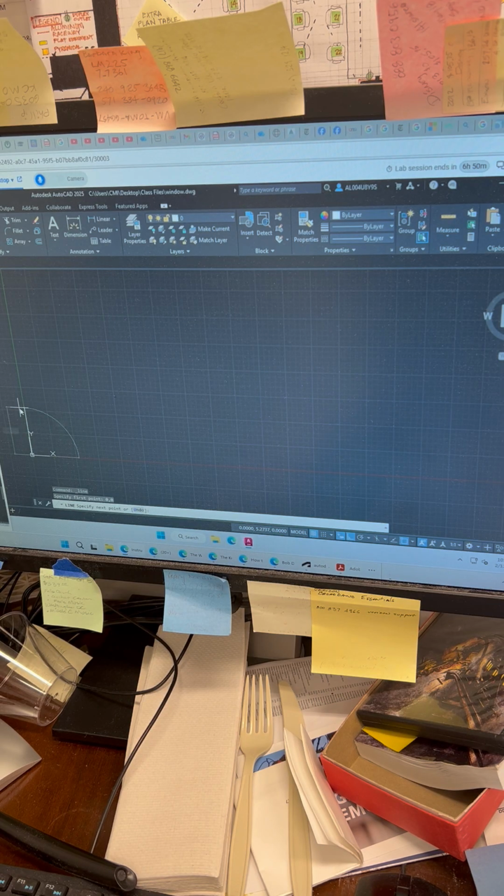All right, now move your mouse around to see that you have drawn a line. Okay, you can see now your rubber band is beginning from 2.5 units away in the Y direction from the origin. Now, just move your mouse to the east.